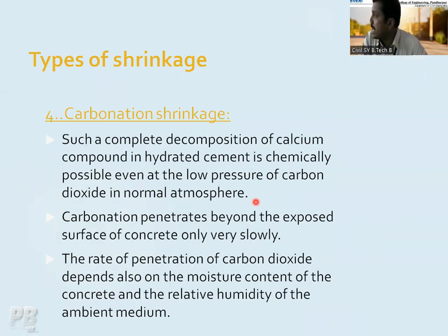The calcium hydroxide is converted into calcium carbonate, and there is a decomposition of your other compounds. Due to this decomposition, there is a reduction in the volume of your concrete, and that particular shrinkage you call the carbonation shrinkage. Please remember this. What is the carbonation shrinkage?